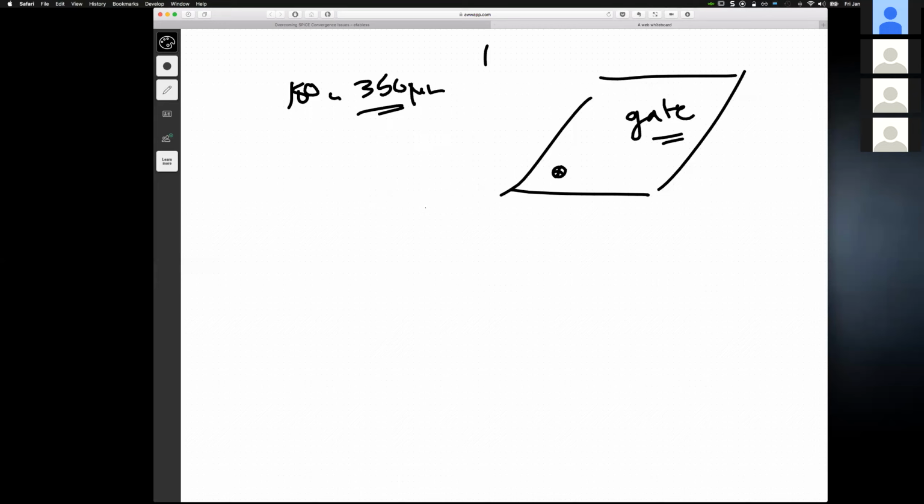That becomes very common when you go down to processes like 45 nanometer. The whole gate oxide integrity effects and the defect density related, we have to put rules in based on the sizes, just based on the statistics of the process, not because of optics or anything else, but the statistics.